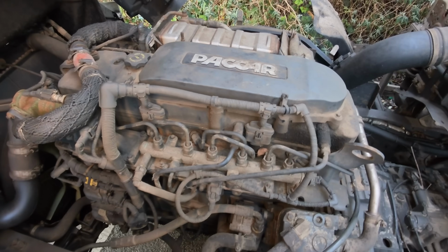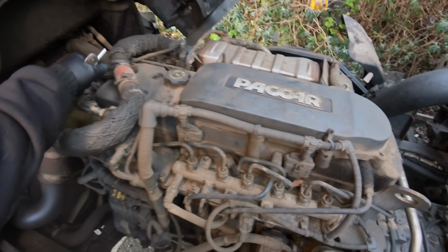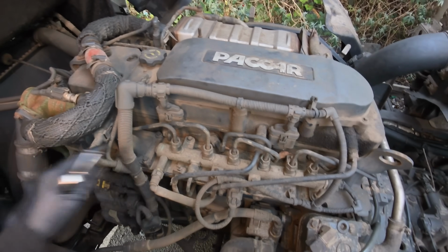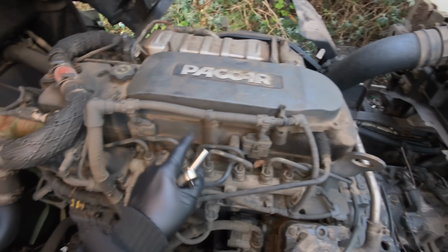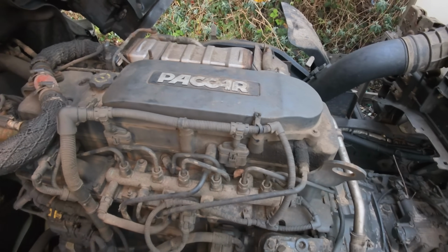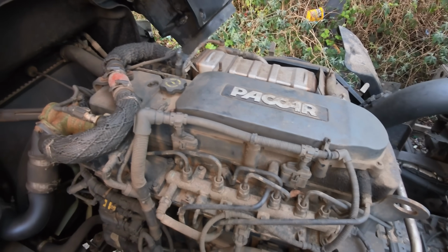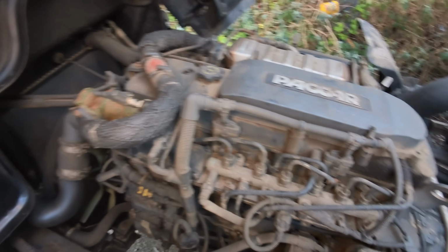This is our PX7 engine. We'll get the crankcase filter out of here, this pipe from the EGR cooler to the EGR valve off, these two electrical connectors here, these two breather pipes. And then we can get the rocker cover off and see what damage has been done in the engine. The hardest part of this job will be getting this bracket off the front, because sometimes them bolts don't like to play ball, but let's get into this.